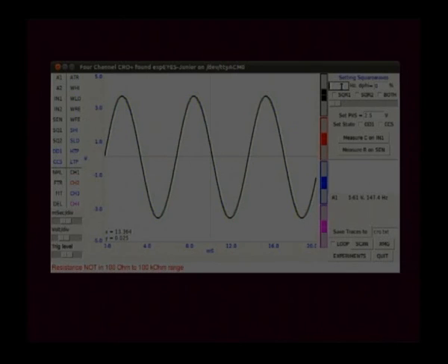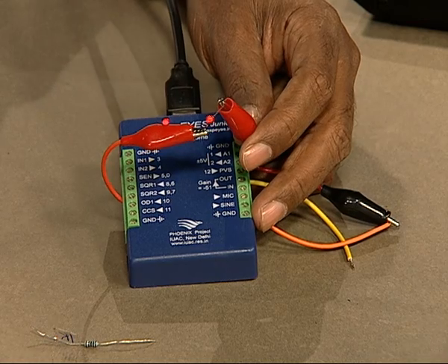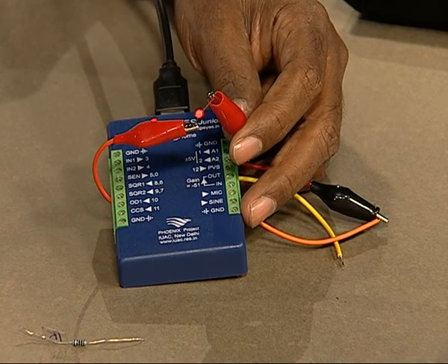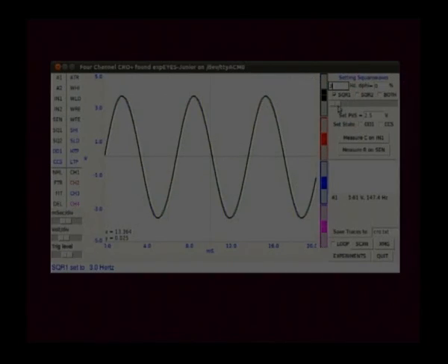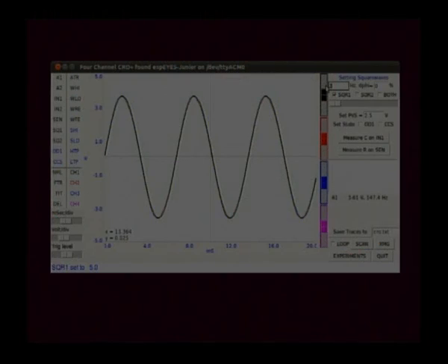Here you can see there is a field where I can set the frequency. I will set it at something like 3 hertz. So, enter the frequency value and check SQR1. You can see that it is blinking at 3 hertz, and using the slider also you can change the frequency. See, when it is blinking at a higher rate you cannot see that, and you can also set it to say 0 hertz.